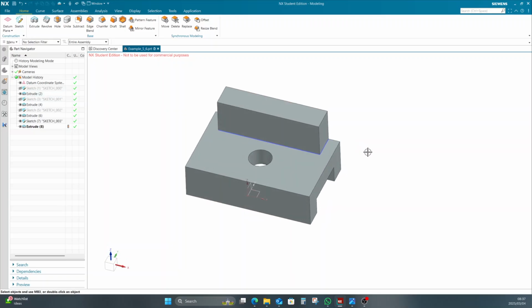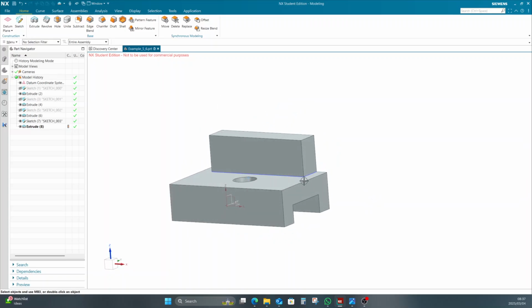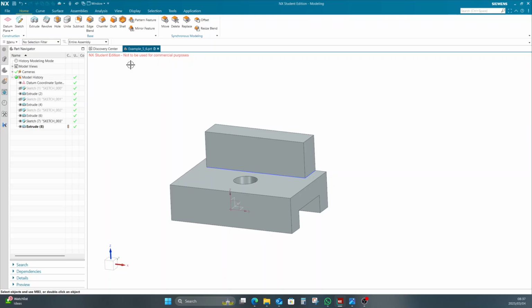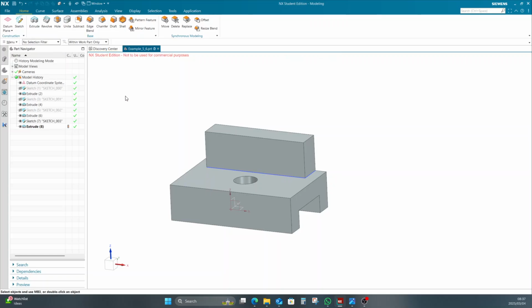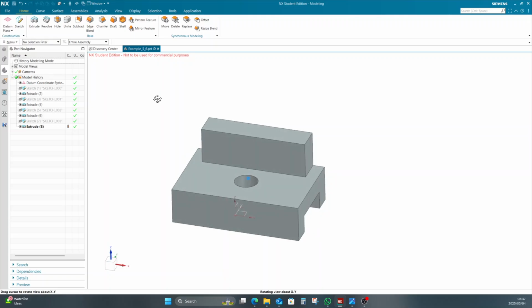enter the answers into Ifundi, because the mass, if it's not united and you say, okay, I want the mass of this part, and you just click on this one, it will only give you the mass of that part if it's not united to this part. So always at the end, make sure that everything is united. You'll see if you click unite and you drag it over this body and everything highlights and it says it's a single body, then you know that it's united to each other. So that's quite important. So I'm just going to hide that sketch.